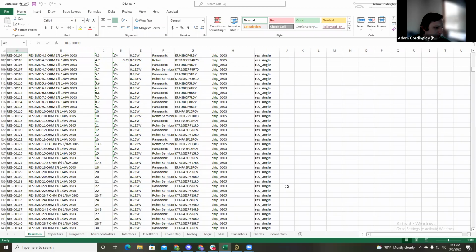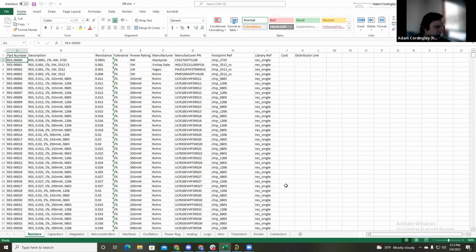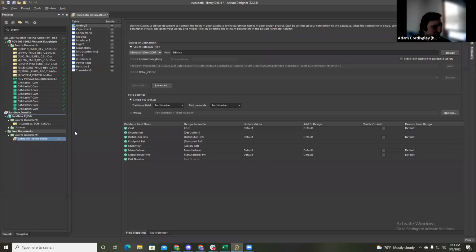There was also just a source of confusion, because Altium had to compile a database or build your libraries from a database every time you ran something. This seemed a little more organized, to compile them to integrated libraries. Then you can distribute those integrated libraries in any way you want, via Google Drive or Dropbox, or put them on a flash drive and hand them out, whatever. Obviously, you wouldn't do the last one.